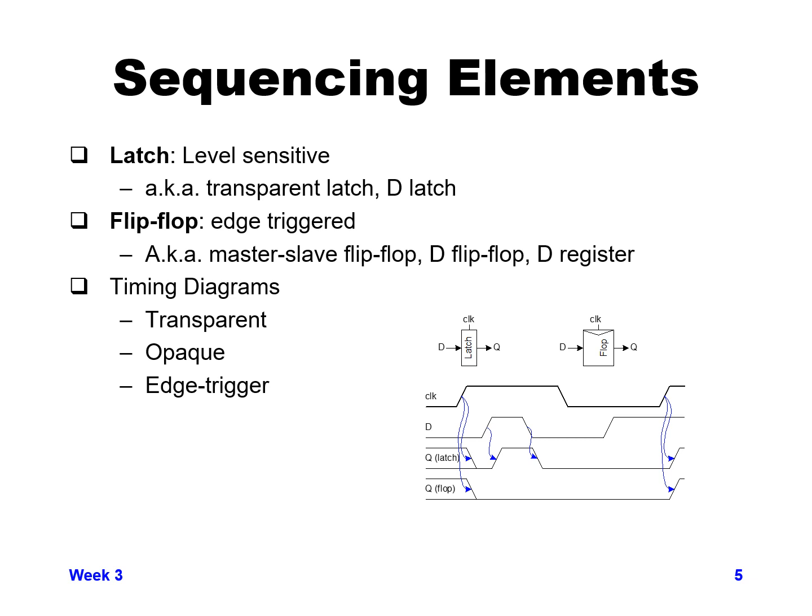So now if we continue following the waveforms along, clock eventually goes low, and when it goes low, the value of D was low at that time. The value of Q was low because it was following D. And then a little bit farther on, the data value goes high when clock is still low.